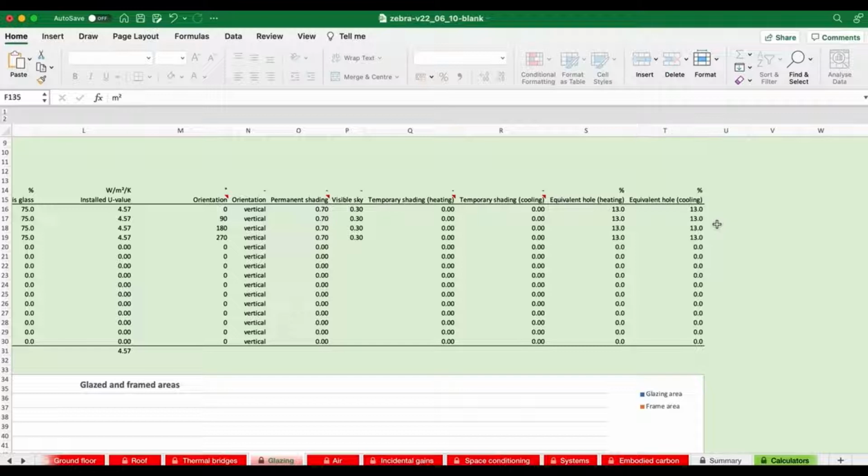Okay, and there are a couple more technical things which don't show at complexity level 1, but do show at complexity level 3. But only 13% of the light is getting in if you hadn't made some of these more complicated assessments of the glazing. And this is why it's critical to get your glazing detailed correctly, even at this very, very early stage of design.